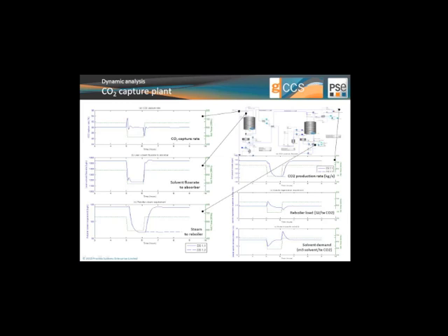And this also can be seen here on the CO2 production rate. Again, it takes about this half an hour that we saw on the power plant side to go back to the steady state. And again, when we move up to 100% load, these disturbances are also appreciated in the reboiler load, basically in the consumption in gigajoules per ton of CO2, and then further down on the solvent demand.